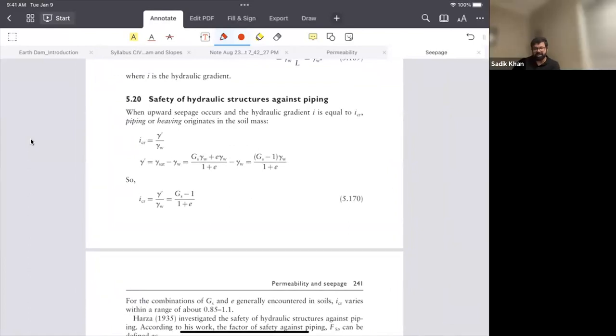Yes. So do you need to check the factor of safety against sliding for an earth dam? We should. I mean, yes or no? I know for a retaining wall, yes, but for an earth dam, no, it's earth, so it can't slide. It can slide. An earth dam also can slide if you have a washout.